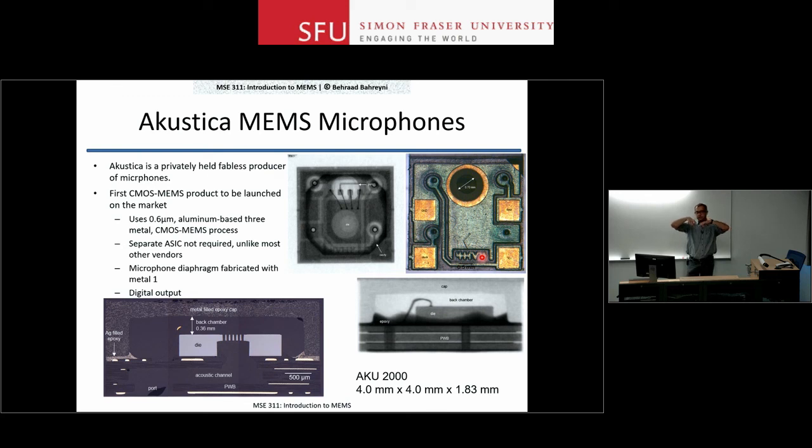The metal layers are usually between dielectrics. So they created patterns of these metal layers such that you could get a more or less membrane-like structure, released the membrane by removing some of the silicon underneath, and created the membrane that responded to pressure.